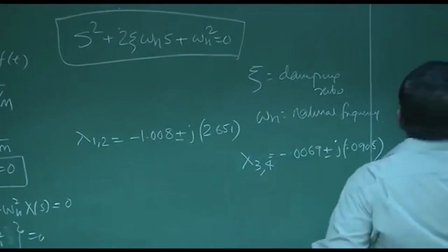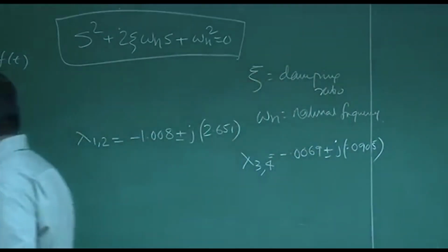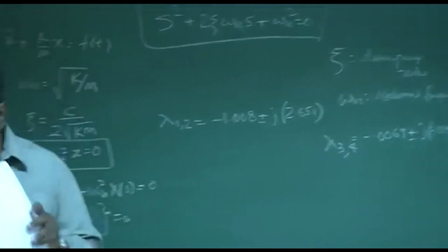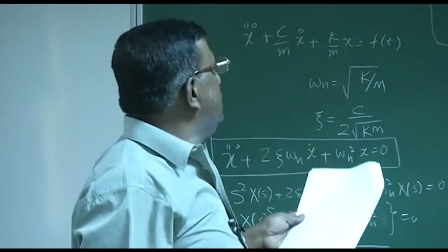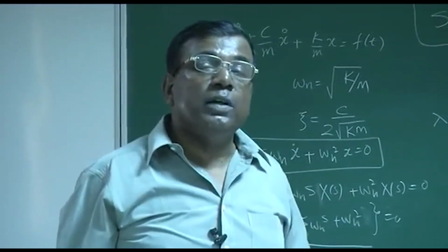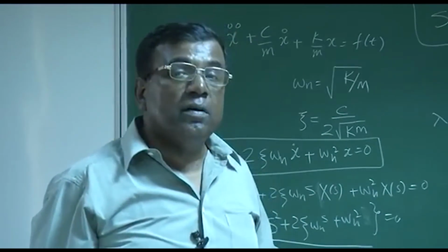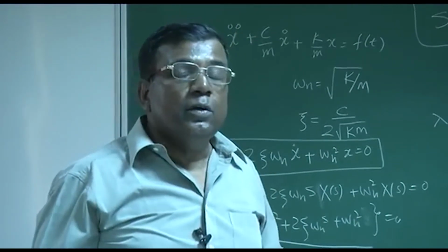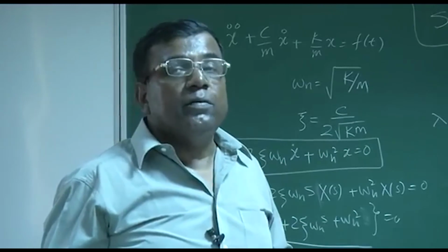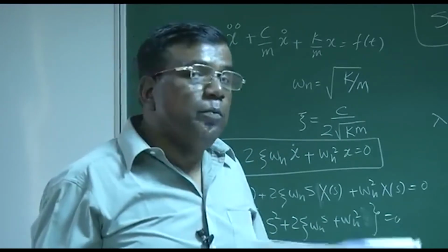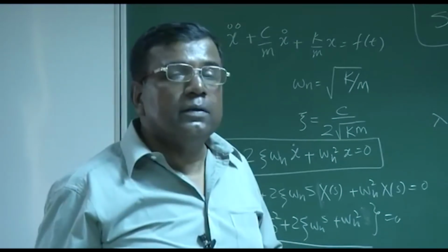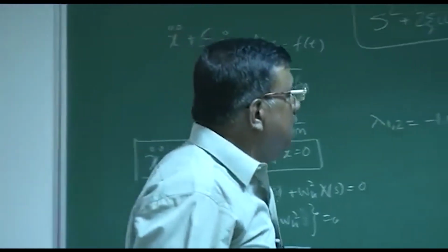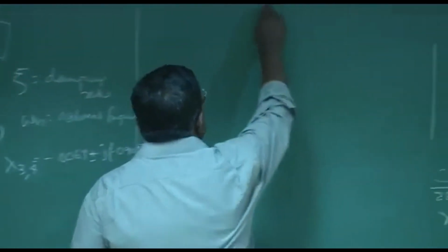Typically, you understand one thing, that for the longitudinal case, the solution for that s4 plus bs3 plus cs square plus ds plus e equal to 0 will generally give two pairs of complex conjugate roots. The moment you see two pairs of complex conjugate roots, you know this corresponds to the longitudinal case. Okay? And you'll find roots are also given like this.